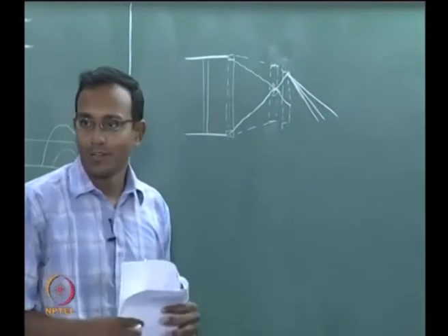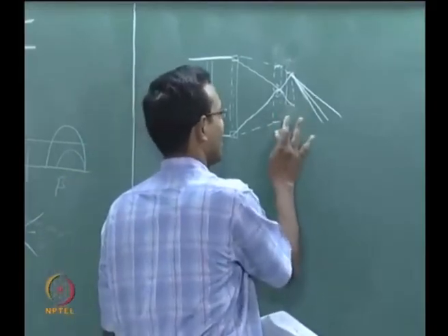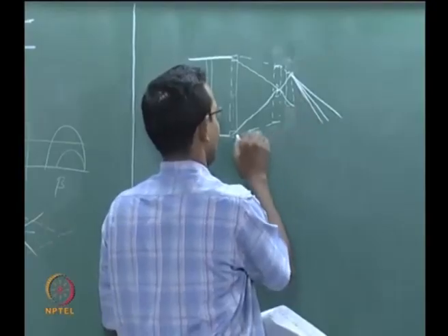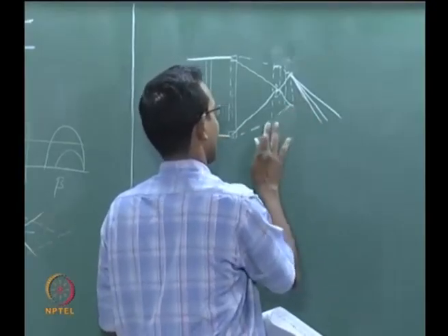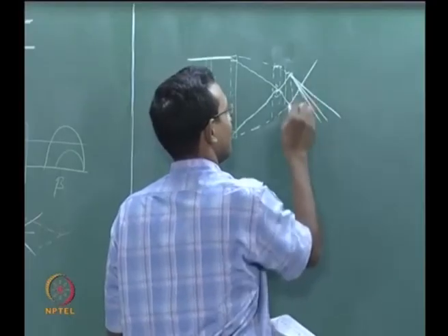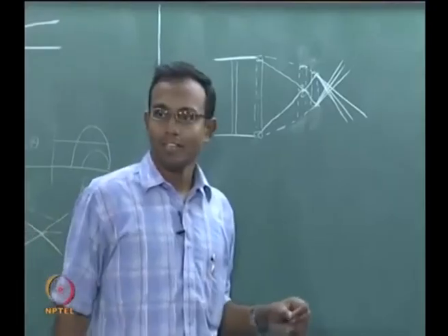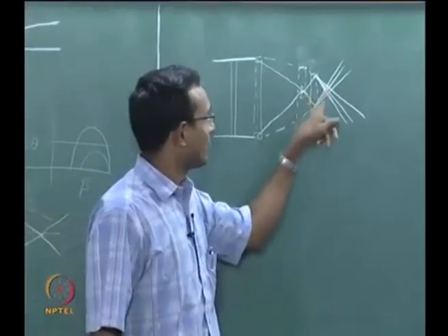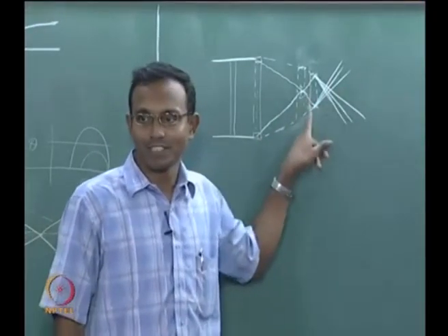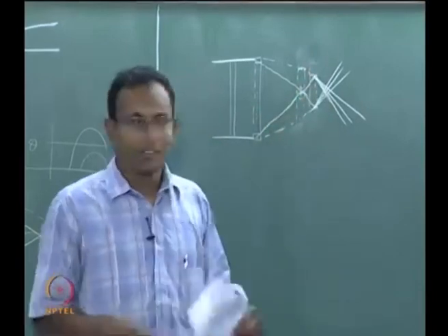They are going to run this way, and similarly the same thing is happening on the other end, and they will also send out an expansion wave fan like this. There will be a whole bunch of expansion fans created, one from this end, other from that end, and they are going to run across.